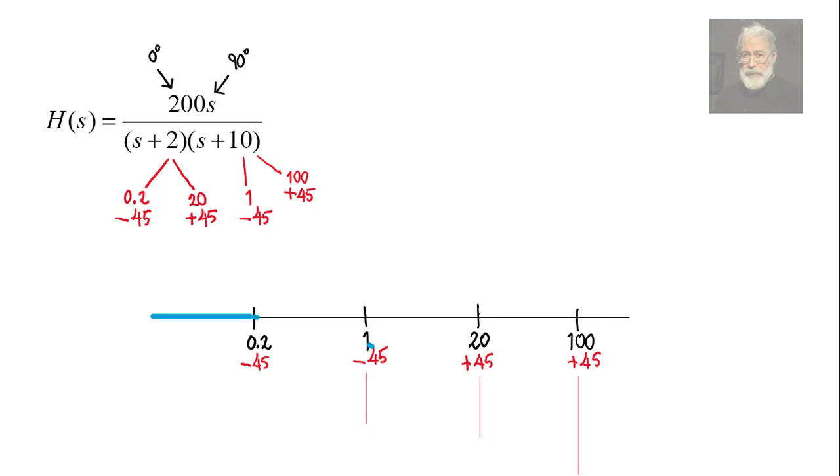So it enters horizontally with what values? Well, the value is 0 plus 90 is 90 degrees. And then it adds negative 45 degrees per decade, and then plus another negative 45 degrees per decade, so that is a slope of negative 90, plus 45, that is just a slope of negative 45, plus 45, that is 0. That is the general shape.